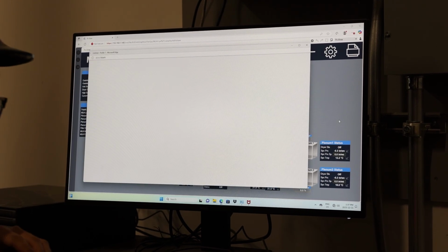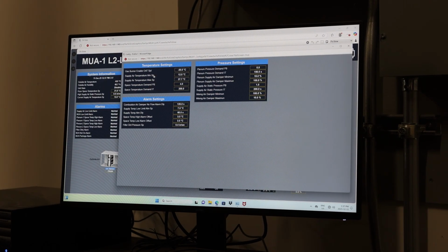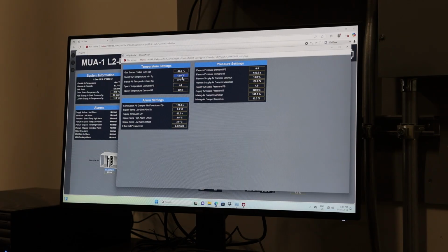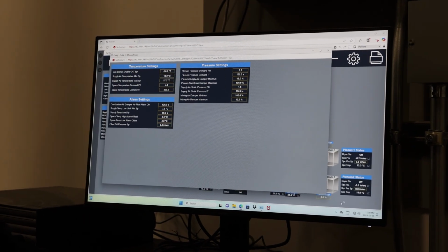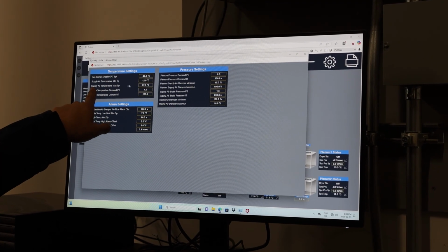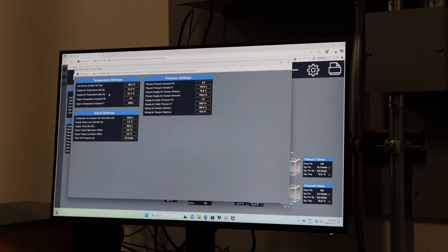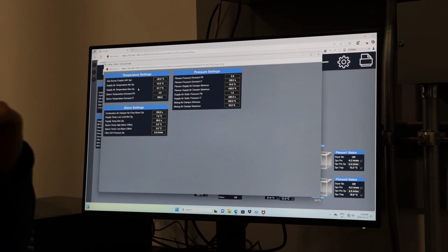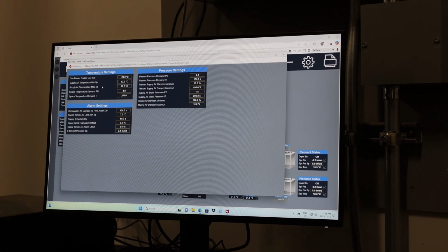What that means is it takes the average space temperature and supply air temperature will have a minimum set point and maximum set point. So that means if the space is too cold, supply air temperature will not go to 37.7 immediately. It goes gradually, slowly. Because once the space temperature is satisfied, it stops at that set point.